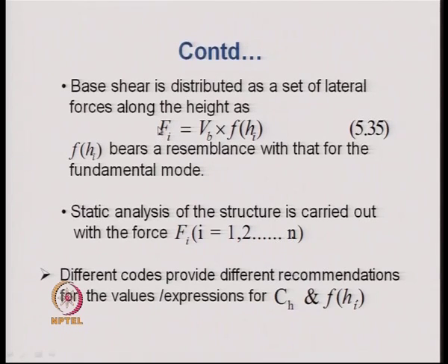After we have obtained these forces Fi for different floors, this force is applied to the structure statically in order to obtain the values of the internal forces in different members of the structure, and those forces may be combined along with other forces, that is the forces due to the dead load or live load. Then we obtain the design forces for individual members of the structure.